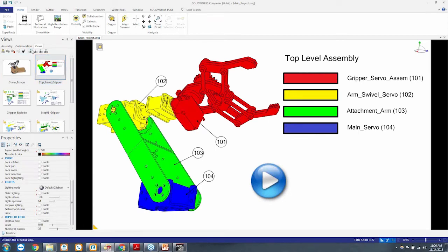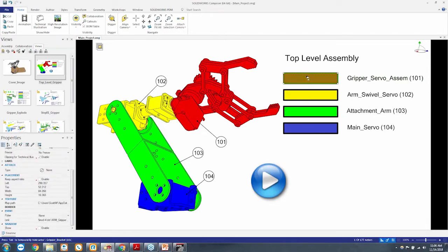Activate this slide here. And what I have going on is just a basic balloons, has some BOM IDs on these components. I got my text here that says this is the assembly, here's the sub-assemblies. Now this guy right here, if you notice when I mouse over, it highlights. So if I select that, come down here in the properties, and keep in mind everything in Composer is based off properties. So we're going to be doing a lot of that today, editing these properties here.